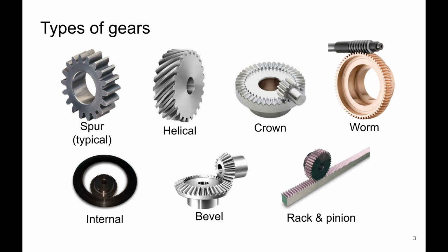However, there are a couple of downsides. The first being it is much harder to manufacture because of the incline of the teeth. The second being that because of the incline, the teeth tend to push the gears apart in the direction of the shaft, so it then makes mounting these gears a little bit more tricky.